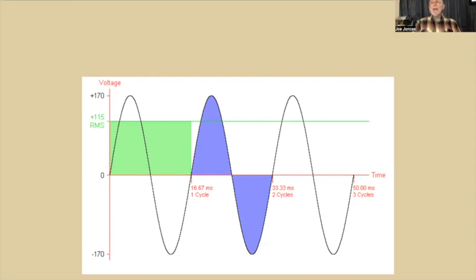And that's how you get your peak envelope power. That's how you figure out what your maximum 100 watts is, or your 1,500 watts is. Or if you're just trying to figure out what a radio puts out, most of them are rated, and we call them barefoot radios, 100 watts peak envelope power. So this stuff is important to you because this is how we figure out what the power output of our radio is.